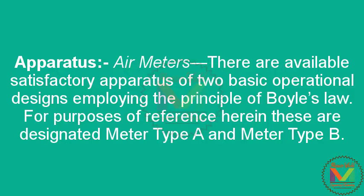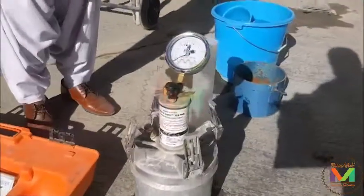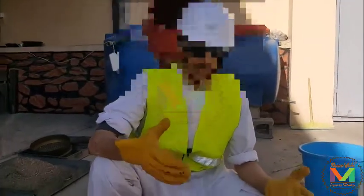Now I'm going to give a little information regarding the apparatus. As per section 4.1, air meters, there are satisfactory apparatus of two basic operational designs employing the principle of Boyle's law. For purposes of reference herein, these are designated meter type A and type B, but we are performing the test by the type B method. In section 4, the apparatus shall consist of all the equipment we have here.